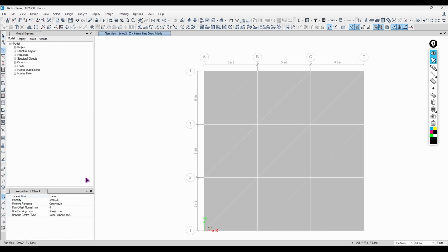You're going to draw something like a beam, but it's not actually a beam. It's called none. What happens is it puts a frame, but it has no thickness, no width, no height. It just has the length you define, but it has no sectional properties. Moment of inertia is 0. The first moment of area is 0. Everything is 0. So when it goes to the stiffness matrix, when it's solving the analysis, it's not taken into consideration.